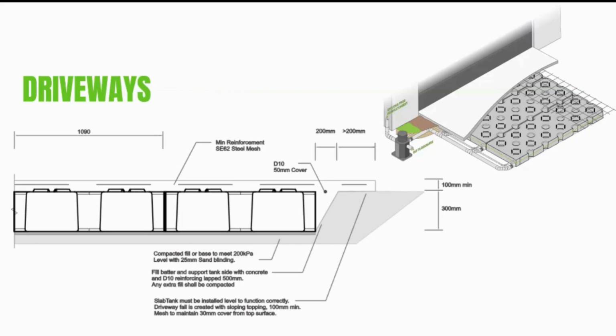What does having large volumes of water passing in and out of the subfloor do to the H1 value, as the water temperature will affect the slab like a giant radiator? If there is cold water coming in and out constantly during a heavy rain period, the cooling effect would be considerable.